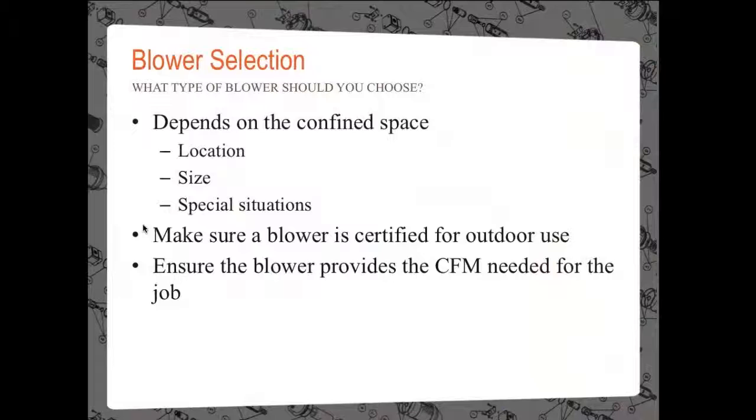The next thing to understand is how to evaluate a blower. Pay attention to the CFM, cubic feet per minute specifications after ducting is attached to the blower, not free air delivery.